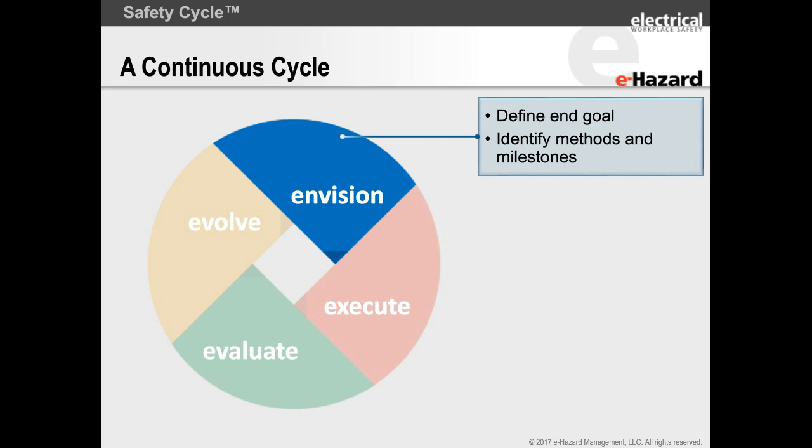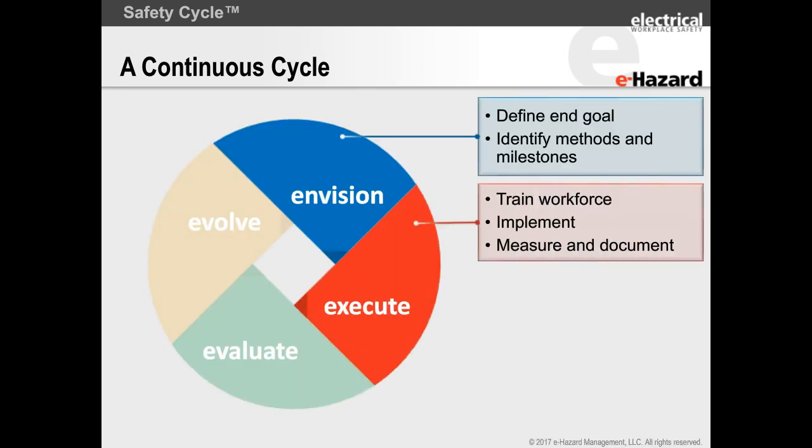We want written documentation of what our PPE is going to be and how we're going to use it, very clear for the worker and very clear for the contractor coming in. That's another problem sometimes. People have contractors come in who don't actually do electrical work. They hire a contractor for it. Electrical contractors tend to be really good. Sometimes manufacturers' contractors that work on equipment don't have the right safety training. So be careful about all those contractors. Write your electrical safety program into your contractor requirements and make sure that you're following up.